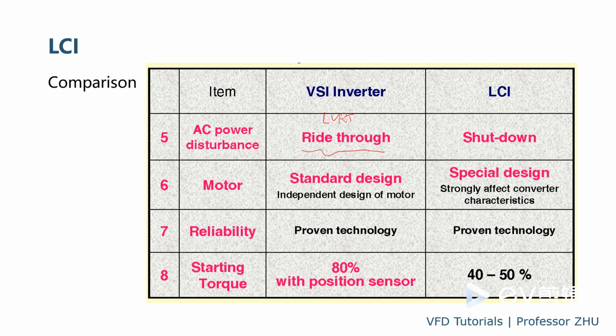And the motor. With VSI, typically you can use a standard motor, especially with the VSI with multi-level output. You can use an existing motor or old motors. But for the LCI, first of all, you can only work with a synchronous motor because you need to overexcite it to get the current leading the voltage.